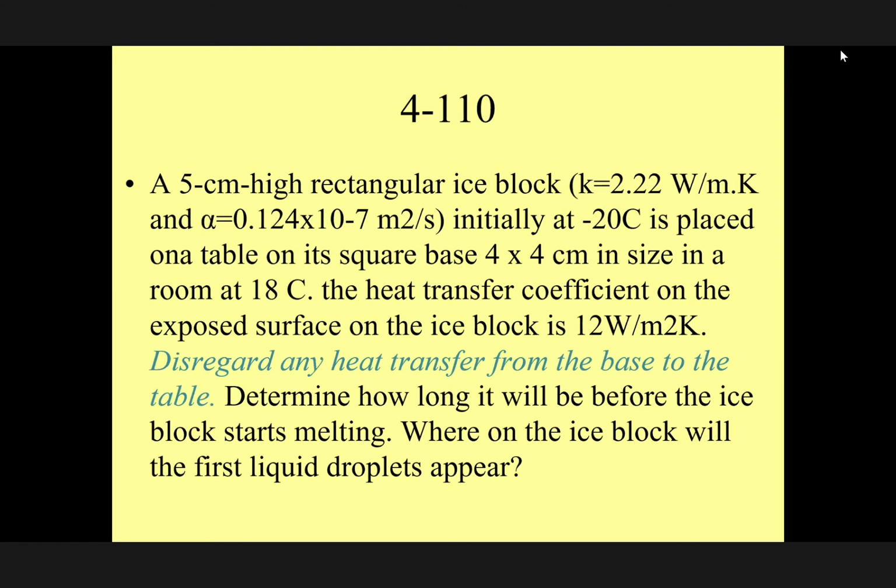Therefore, it means I cannot use the simplified equation. So you could use the equation for 452. Tell me, what is the equation, sir? Whatever equation you say, I will take it. It's a transient heat conduction for a multi-dimensional system. Okay, good. It's not a long or infinite wall, so it's a rectangular bar. Therefore, the question that I have here is a solid material.